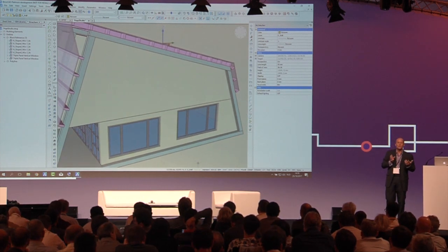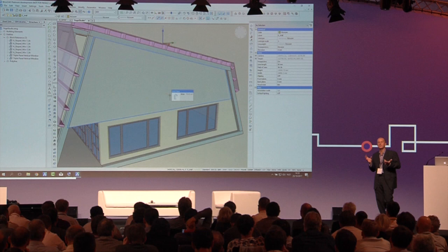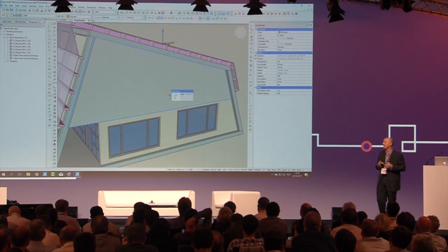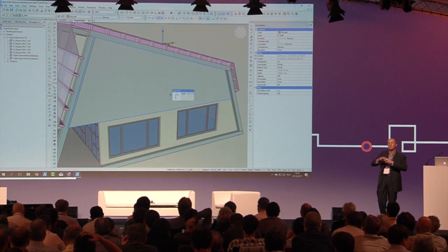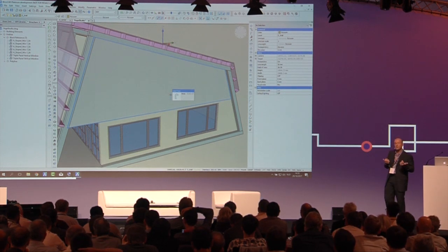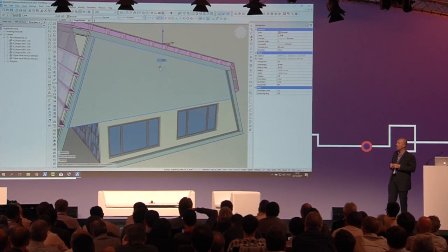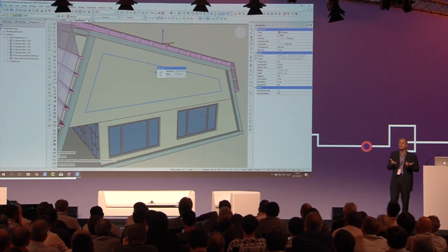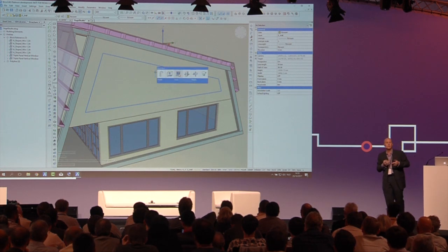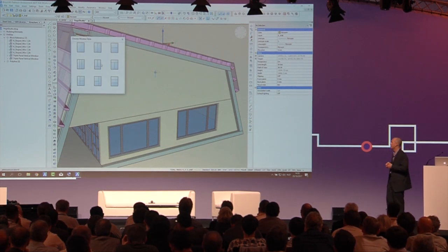Now, the window creator tool doesn't just have to be rectangular windows. And since we've got an exterior skeleton for the structure for this building, we can have a lot more glazing on these side elevations. So we can highlight the boundary of this side facade portion, offset it, create a new boundary, and then we can use the window creator tool.